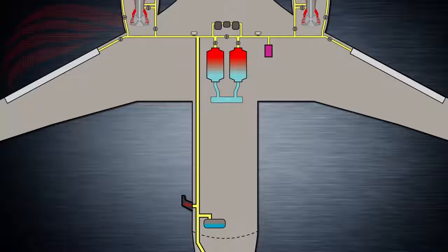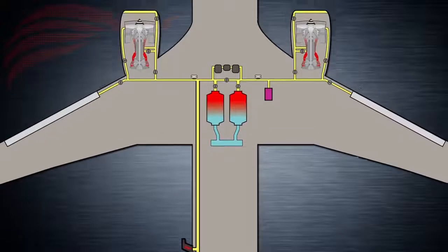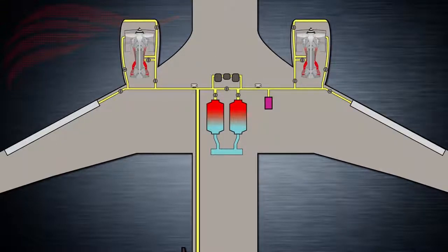It's not necessary to memorize what system is associated to what side of the pneumatic manifold. To summarize the important bits, we must emphasize that the ground pneumatic power connector is linked to the right side, and that the APU bleed system is linked to the left side of the pneumatic manifold. The Engine 1 and 2 bleed air systems are associated to the left and right sides, respectively.